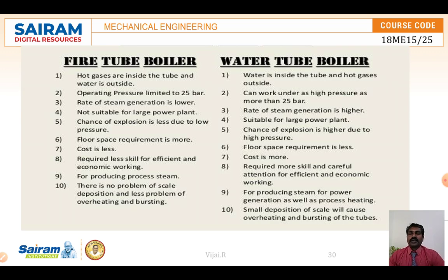Here the difference between fire tube and water tube: in a fire tube, hot flue gases are inside the tube and water is outside. In a water tube, water is inside the tube and hot flue gases are outside. Fire tube works limited to 25 bar, but water tubes work at more than 25 bar. So the fire tube is not suitable for larger pressure, but water tube is used for larger power